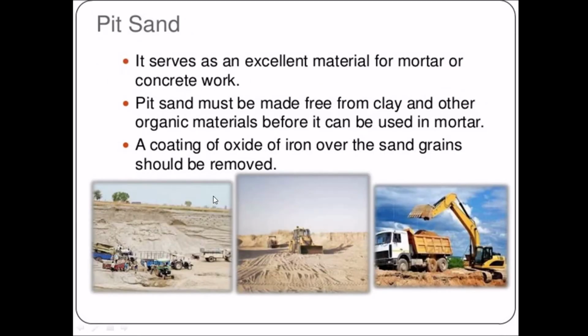It serves as an excellent material for mortar or concrete work, and pit sand must be made free from clay and other organic materials before it can be used in mortar. Coating of oxide of iron over the sand grains should be removed.